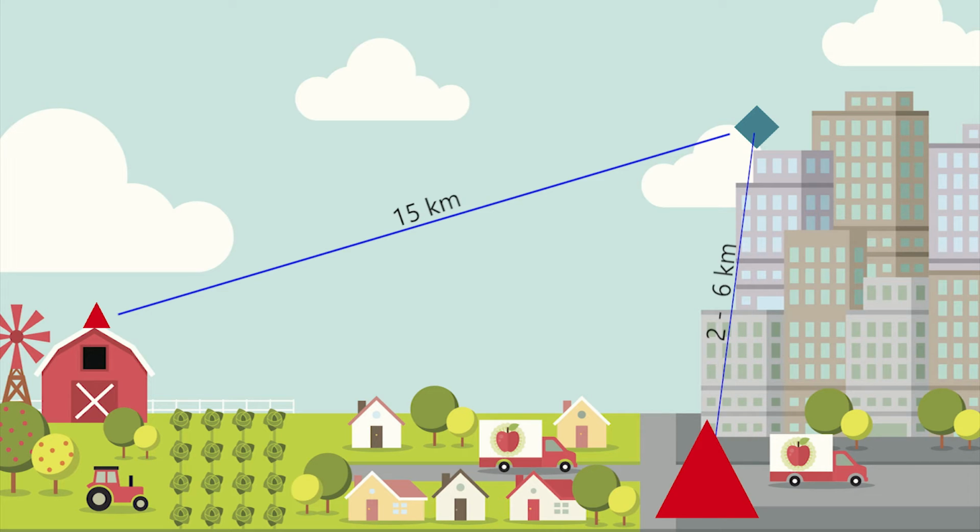We say noisy here because of all the other users and all the electrical interference a modern urban environment produces. There are, of course, the other problems with radio waves, that they don't pass easily underground or deep inside buildings, particularly metal frame buildings. Tall buildings can act as radio reflectors, causing the signal to interfere with itself. Experience this for yourself by shouting across a large sports stadium. And of course, the signal gets weaker the further it travels.